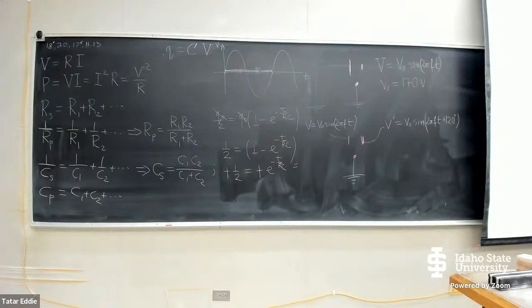To measure the current, you think in a different way. In order to measure something, it has to go through the measuring device. This means that the ammeter, the current meter, has to be connected in series with the device whose current you want to measure.